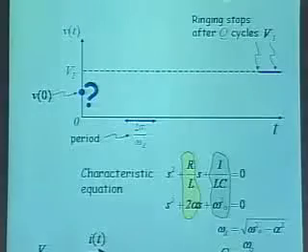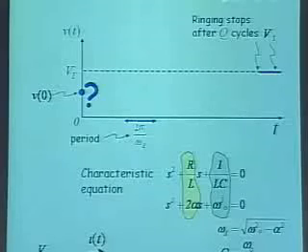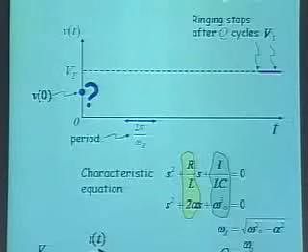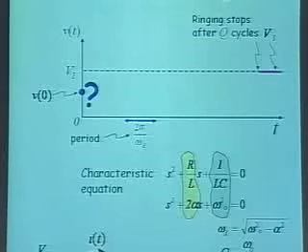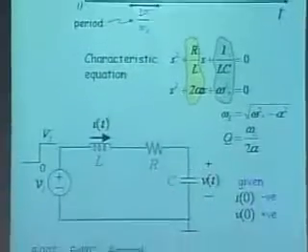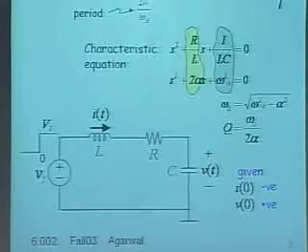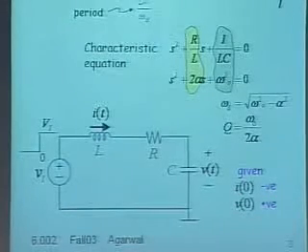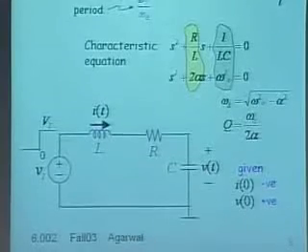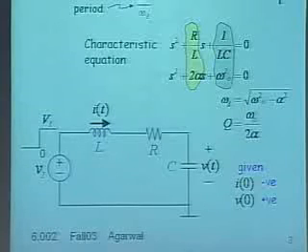Okay, and I started with this point in the last lecture, and I let you think about how you can stare at the circuit and intuitively figure out whether this goes down or that goes up. Here's the insight. Let's stare at this for a minute, purely through intuition. The capacitor has a voltage V across it, because I'm telling you that it has an initial voltage V. Now, I want to find out, at time t equals 0 plus, in which direction does the capacitor voltage go, increase or decrease?